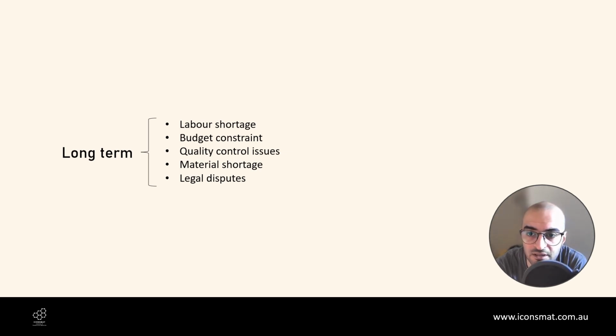If you're planning to construct the column or the beam, just cross out or mark the areas where the column is going to be located. Ask the quality control personnel to come along and certify the location of the columns or other aspects of the construction. Quality control is not specifically just about placing the column or the beam.